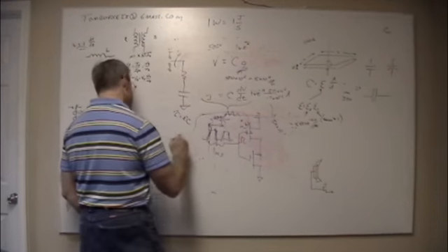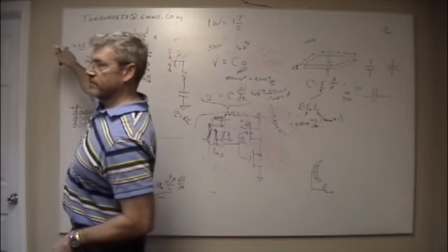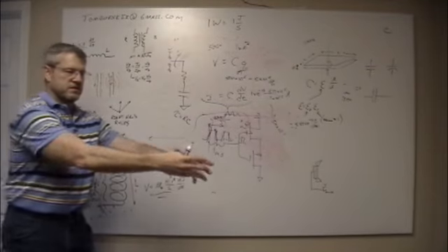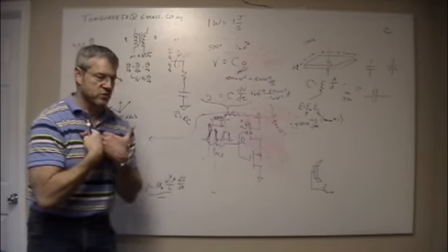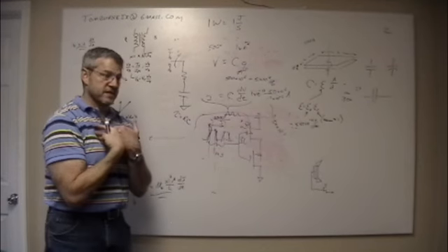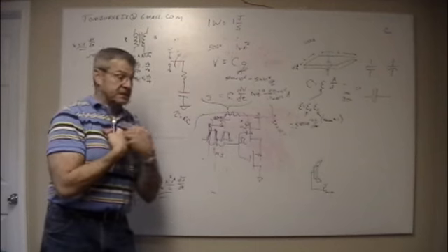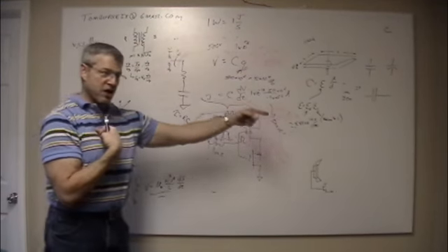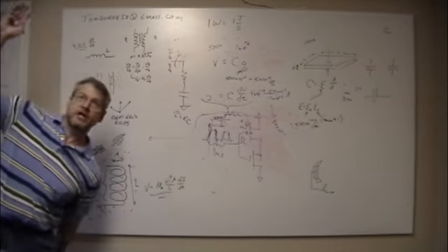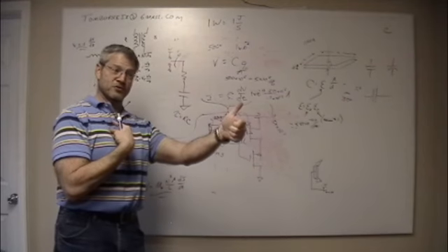The power supply, way the hell back here, remember we talked about going from the front of the breaker box to here, it can't supply enough. There are two ways of doing a power supply. There's source sensing and there's load sensing. Most power supplies look at themselves and say, yep, I'm putting out 5 volts. Yep, I'm still putting out 5 volts. Your load out here on the other end is like, I only got 1 volt. Hey, I got 8 volts now. Oh, I've only got 1 volt. Hey, I've got 8 volts. And your power supply sitting here going, I got 5 volts.